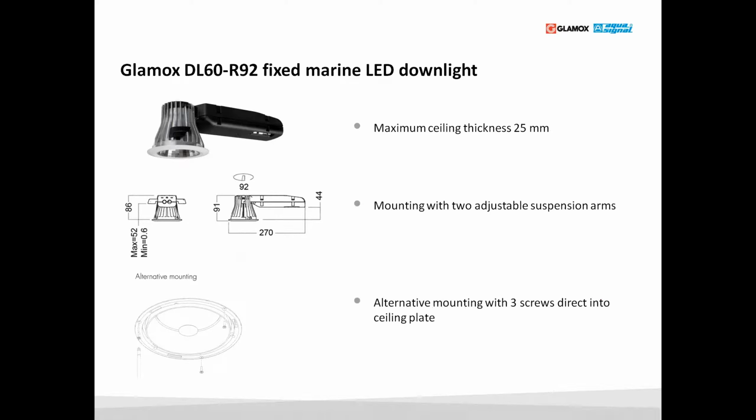This R92 is for maximum seal thickness 25 millimeters. That means that this can't go over 25 millimeters. So it's limited. And that's also stated inside our web, maximum sealing thicknesses, because if you look at the dimension drawing here, you can begin to think, oh, I can cover 44 millimeters.